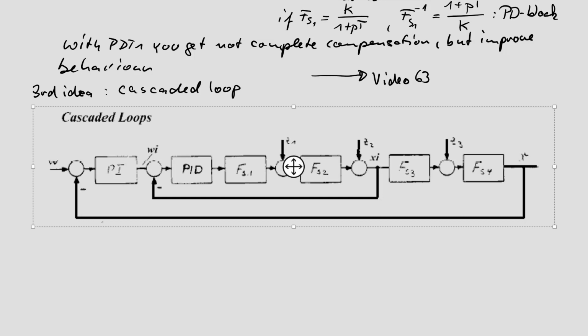Okay, the principle is very simple. What do you need more? You need here a junction point. That means you have to measure an internal physical variable. You need not a disturbance sensor, you need a sensor for an internal value. So you have to change the hardware of your system, or find a position where you can measure internal values.